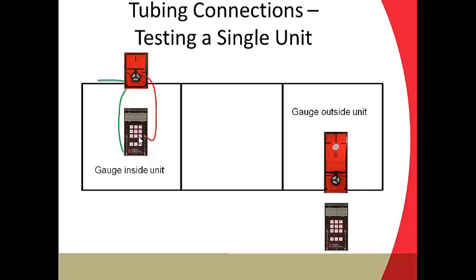So we're actually measuring a pressure and the gauge is converting it to flow. We're measuring the pressure at the flow sensor of the fan with respect to the space that flow sensor is in. So the gauge and the flow sensor are in the same space, so we don't need to connect a tube there. But now when our gauge is outside, we need to think a little bit more about that. We need to measure house with respect to outside. We're outside, so we don't need a tube on the reference, but we do need a tube on the input. So we need a tube going into the house with reference to outside.